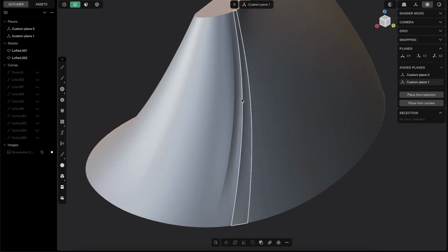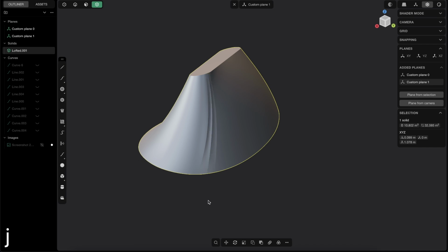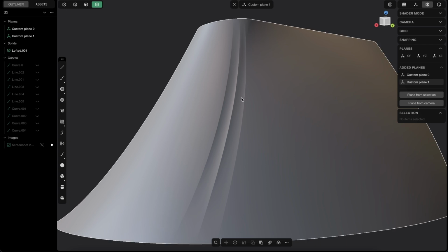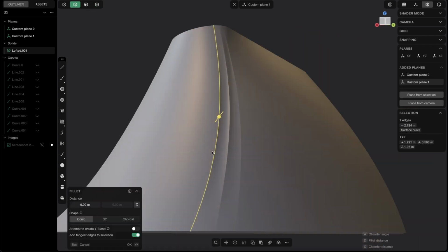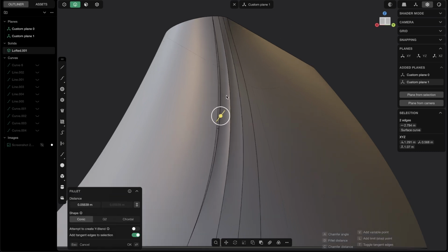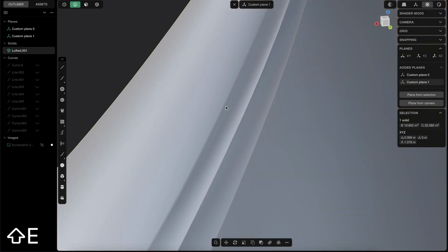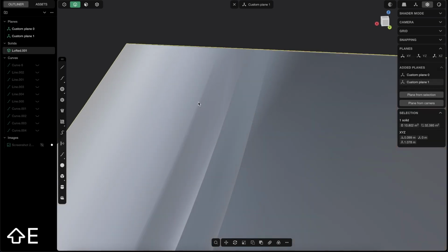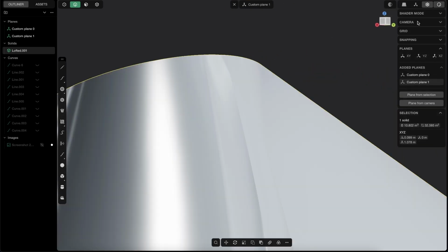Because again, let's select solid mode here and select all the sheets, press J. And the problem is that maybe someone thinks, oh yeah, we can just give it a fillet. You can't, because if you select this edge here and give it a fillet, and let's see it, you see it works, but the problem with that approach is, if we show that, here it looks fine, but here you see that the fillet creates this triangular shape, and you will see it with this mode here.